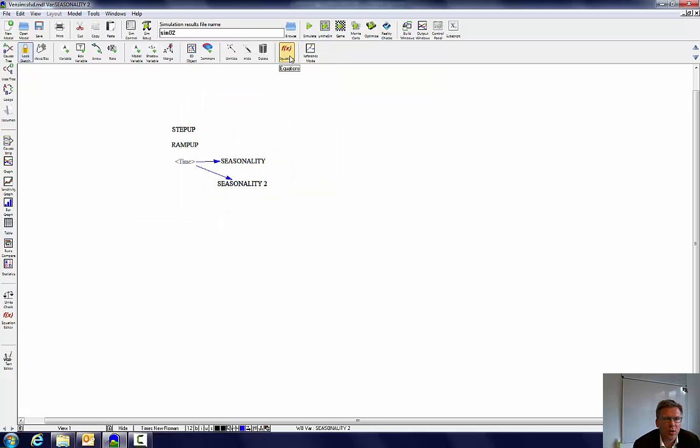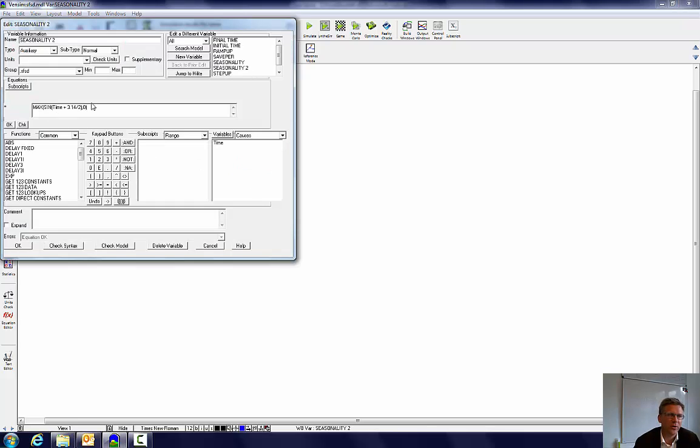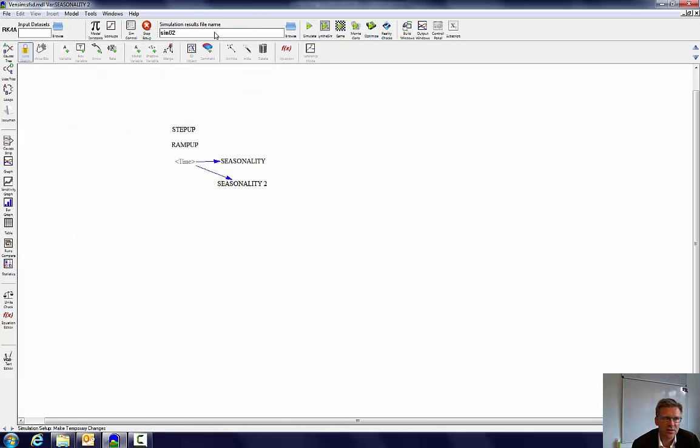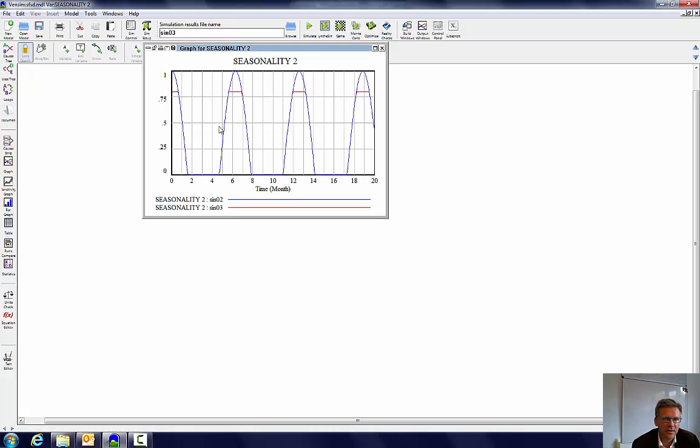Say for instance we do not want these large peaks, but we want to top it at 0.8, then what we can do is use a minimum function to actually set a ceiling. So if I go for a minimum function of this whole function that we already had, or 0.8, then if I do this, you see that instead of having the full sinus wave here, you would actually top it at 0.8.